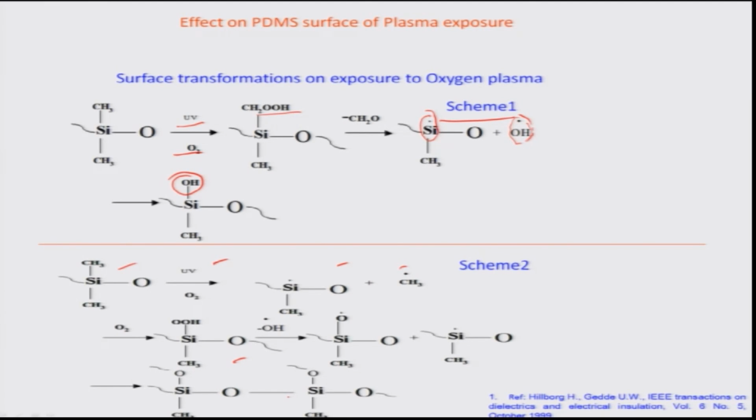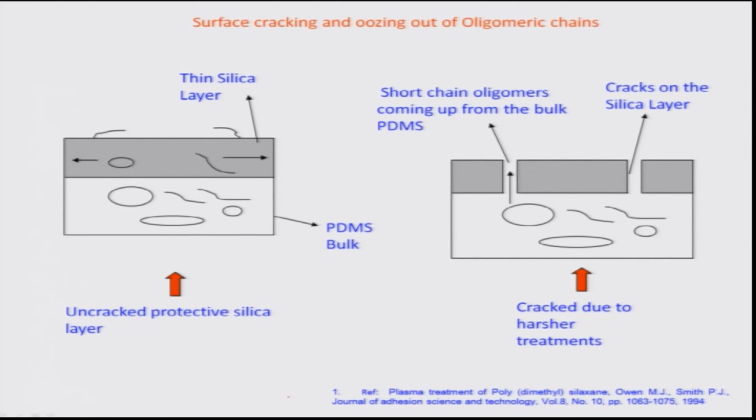So, there are many such schemes which have been studied earlier by people, but the exact window of operation in terms of the pressure and the power of the plasma system would come out by this contact angle analysis, which is a sort of universal scale to gauge whether you would get good bonding strength between the different surfaces which are participating in this particular process.